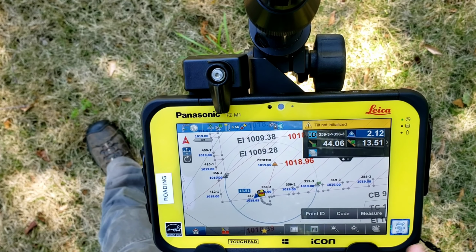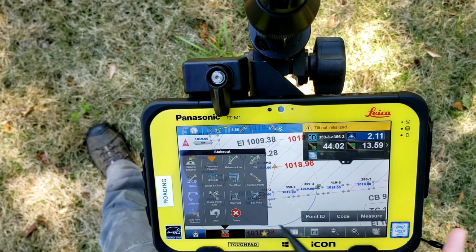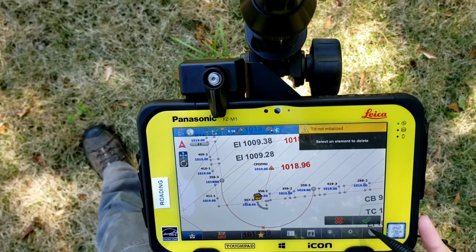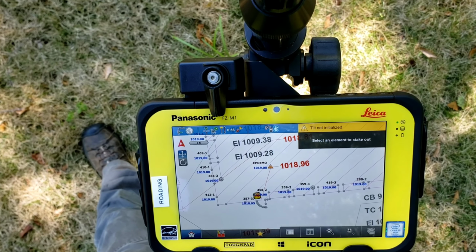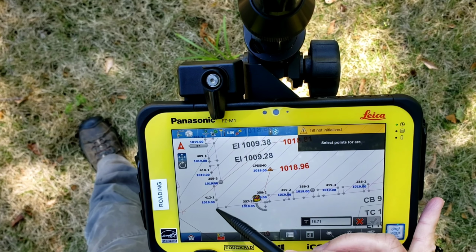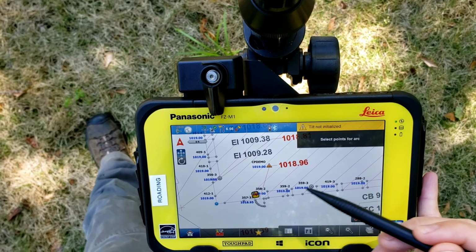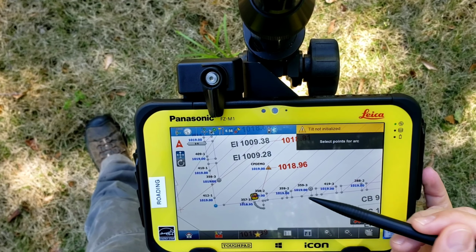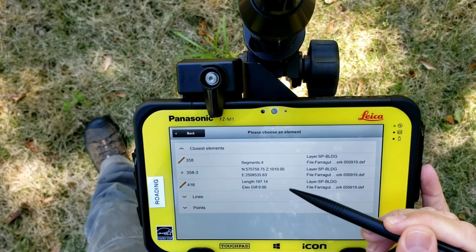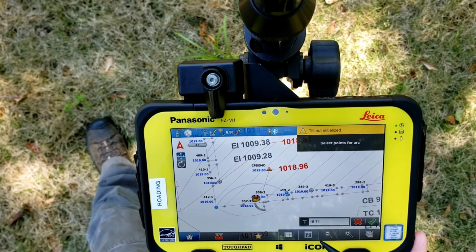So here's the other thing. Let's delete that for right now, and let's do this. So we're going to go back into create arc. Now if you pick 2 points, any two, I'm picking these on the building, which you can use for any, but if you pick 2 points and pick this one here, you can change your radius.